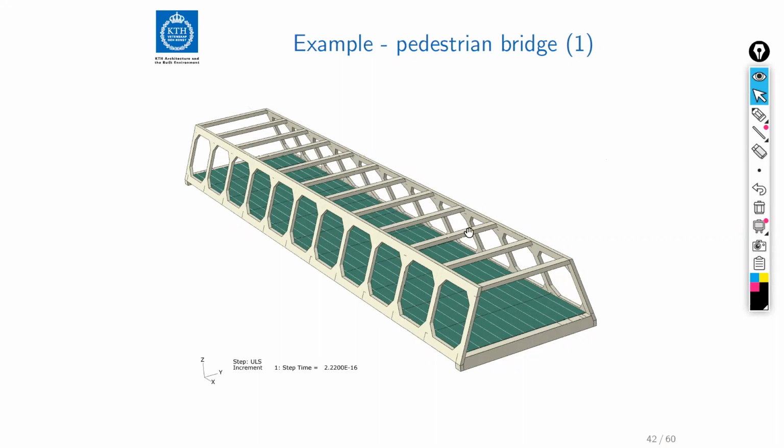Many of these are standardized beams, but nevertheless, in order to mount these together in a good way, you need a lot of internal stiffeners. And then the design code says that if the natural frequency of the fundamental mode for vertical vibration is above 5 Hertz, then you don't need to consider dynamics at all for pedestrian bridges.